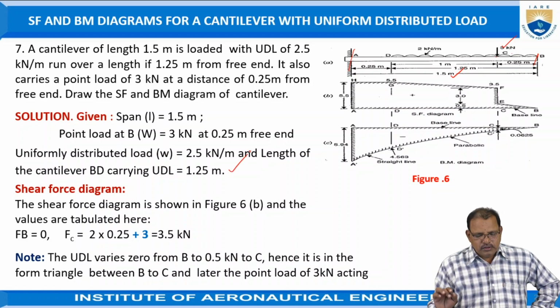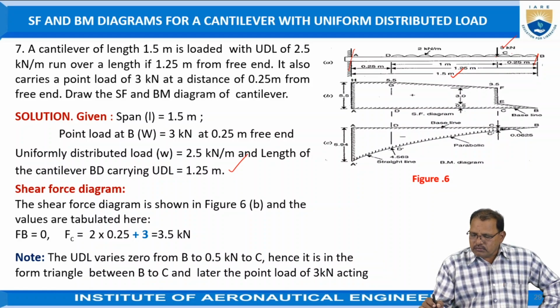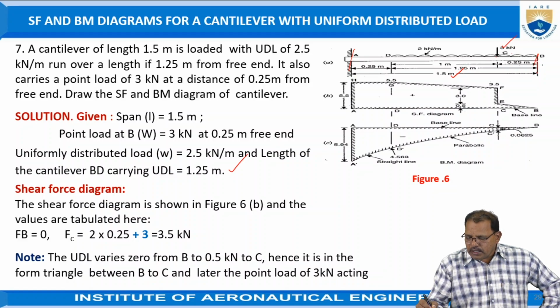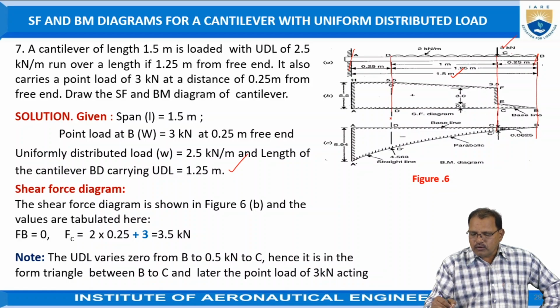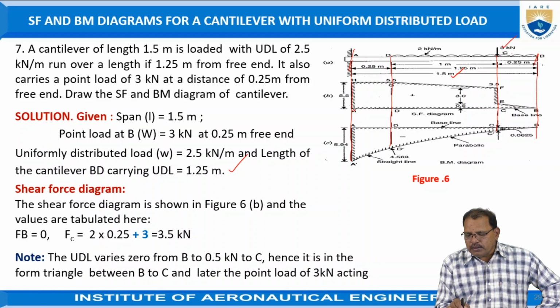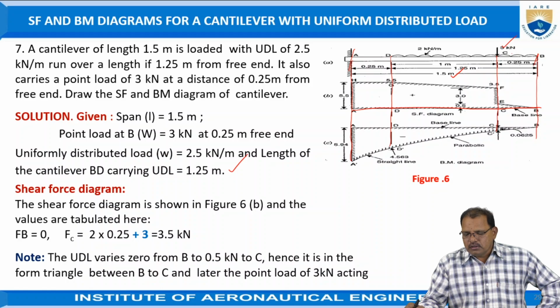Yes, given now. First of all, we have to draw the shear force diagram. First of all, draw the cantilever beam and represent all the forces which are acting on it as shown in the figure. From the point B, draw a line vertical and downward direction. At C, one more line. At D, one more line. At A, one more line as shown in the figure. After that, draw a line AB to represent the length of the beam as an ordinate for drawing the shear force diagram.